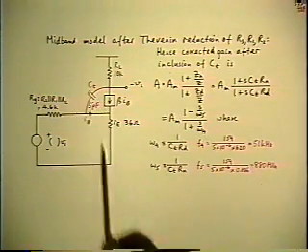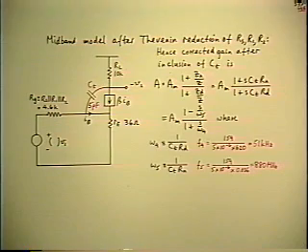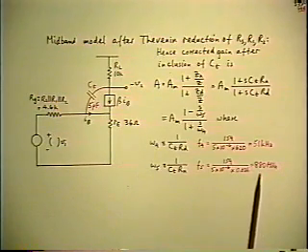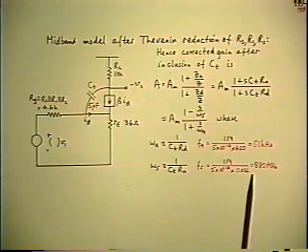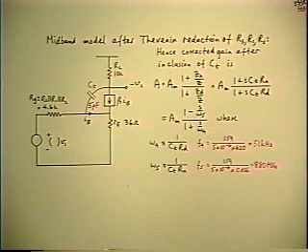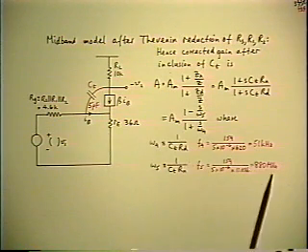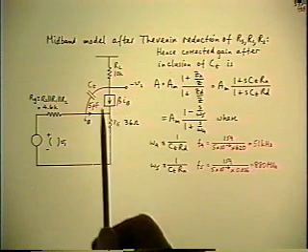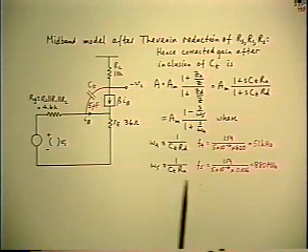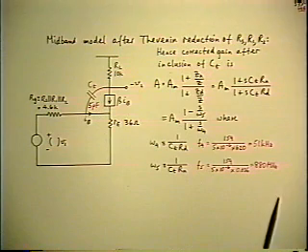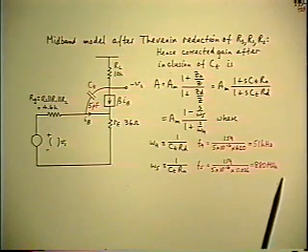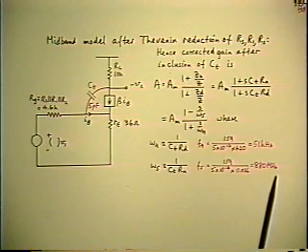And suppose you have both of those things at the same time, bigger capacitor and bigger resistor, then you may be down into the low kilohertz region. So, one thing to think about now is right half plane zero in this stage may not be of any concern, but if you have widely different numbers, it may come into having some effect, and it may be the cause of some difficulties you might have had and not really known why.